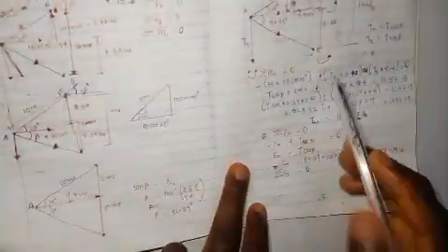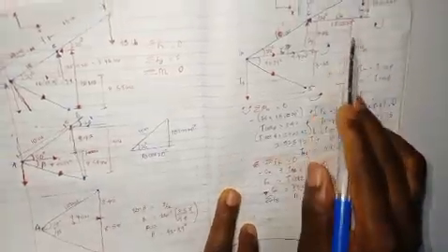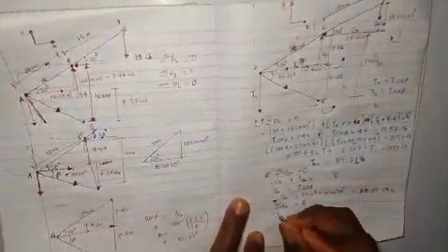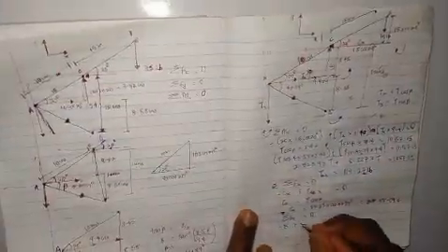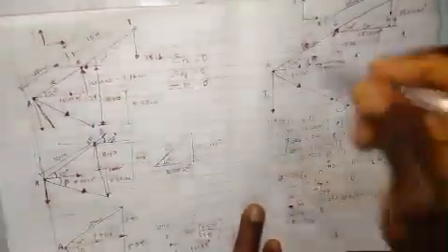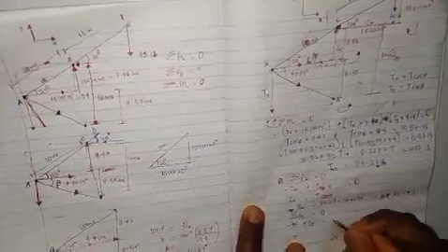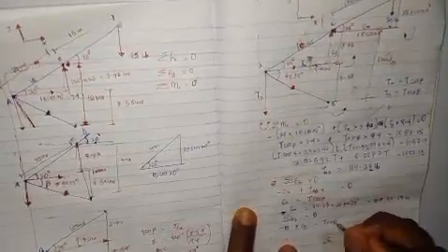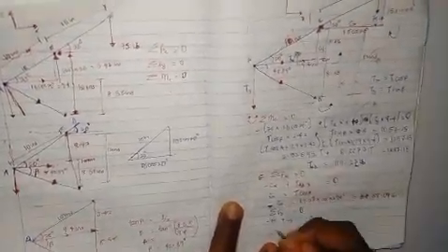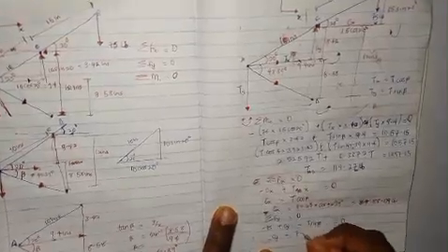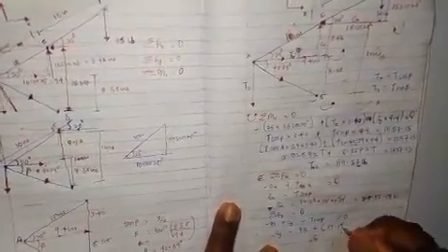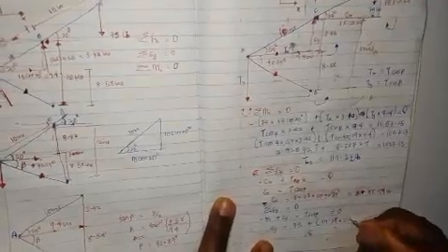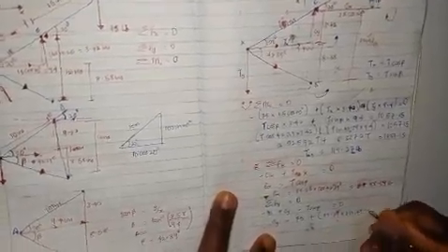So the next one, let's take the summation of force at y to be equal 0. So that means here we will be having the first one. Don't forget this at B is going downward, that's minus 75 pounds. Then this one plus Cy. Then this is coming down, minus T sine beta. Don't forget that's our Ty is equal to 0. So that means our Cy is equal to 75 plus T, which is 119.27 times sine of 42.39.